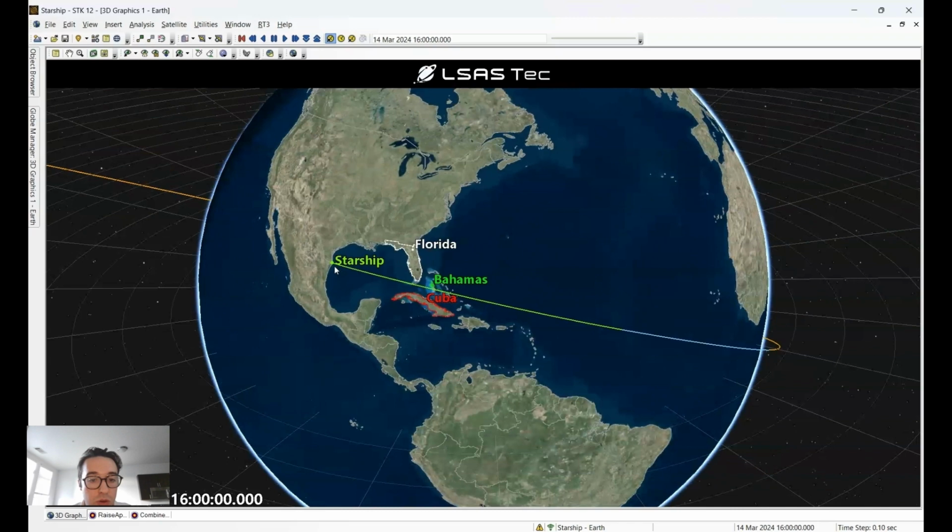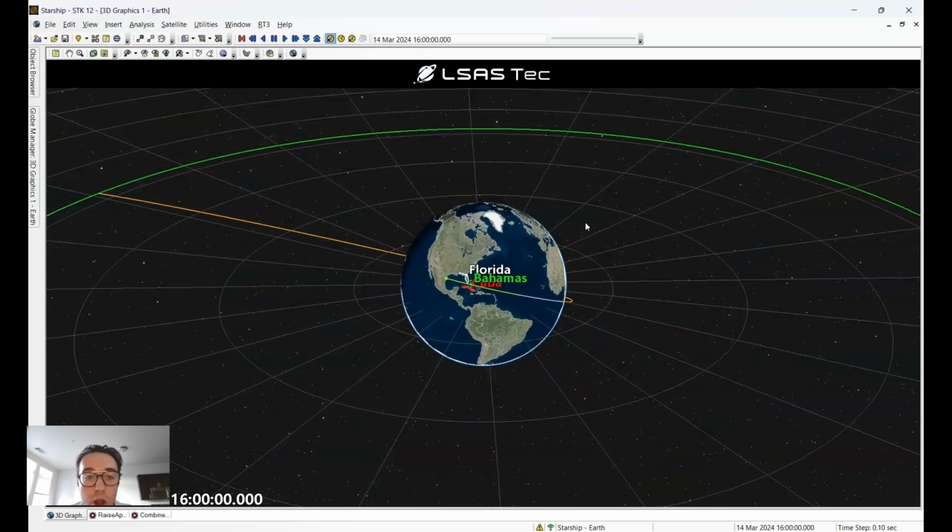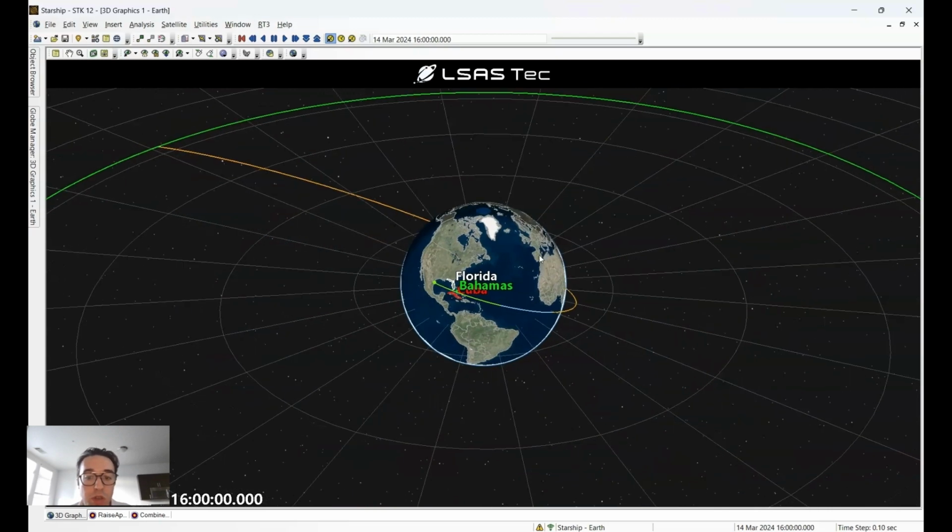First of all, because it defines your launch angle here, the initial launch angle. So it defines how you can avoid having access with your airspaces. And it also has a huge impact on your delta V compared to the downrange distance, for example, because this azimuth at burnout also determines your initial orbit inclination. And if you have a higher inclination at your initial orbit and you're actually trying to get into an equatorial orbit with an inclination equal to zero, then you're going to burn more fuel.